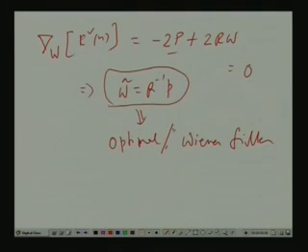So, what you should have? You should try to have some adaptive mechanism by which your filter learns from the data that is coming in and tries to adjust itself by some iterative method, so that finally it converges on what should be the corresponding Wiener filter for a given R and given P. Then again, after a while, if R and P change, that adaptive mechanism will be used. It will further read from the data and readjust itself, so that you get a new R and new P, and you get another corresponding Wiener filter.